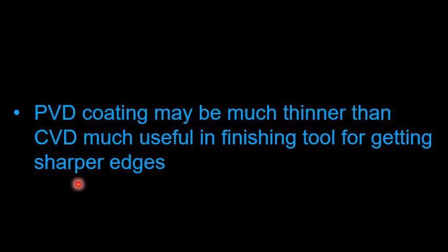In the liquid injection chemical vapor deposition process, you evaporate a precursor material or a source material by heating externally, but you can deposit the material by controlling the injection of the precursor material inside the reaction chamber. So by controlling the injection, you can prepare ultra thin films with the CVD process, but that is usually done at an advanced level in advanced techniques like the liquid injection chemical vapor deposition process. Overall, the CVD process provides you a thicker film as compared to PVD process thin films.